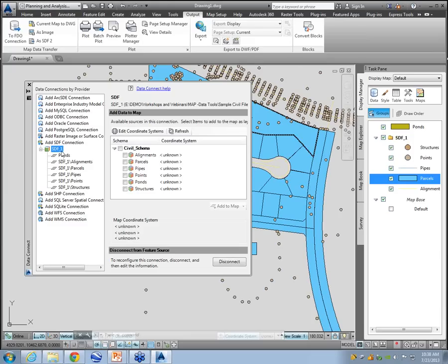So you all know XREFs. If somebody moves the XREF, then I'm kind of hosed. There are a lot of ways to get around that with an XREF. If I put it in the same folder as the drawing file, that gets around it. If I use the XREF manager to change all my paths, I can get around it. We don't have those things here. So you want to make sure that this path never, ever changes. And like that's going to happen, right? You're always going to have some IT person who's going to move things or change something. So how about taking that path and putting it in as a mapped drive?